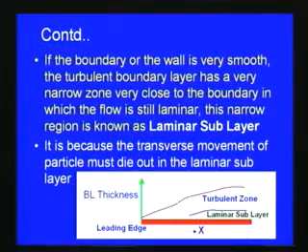We have to consider this also, but most of the time, since the effect of this laminar sublayer is very small and its thickness is also very small, generally it may not be considered. Depending upon the accuracy we need, we may not consider it in most calculations, but if very exact results are required, then we may consider the laminar sublayer also.